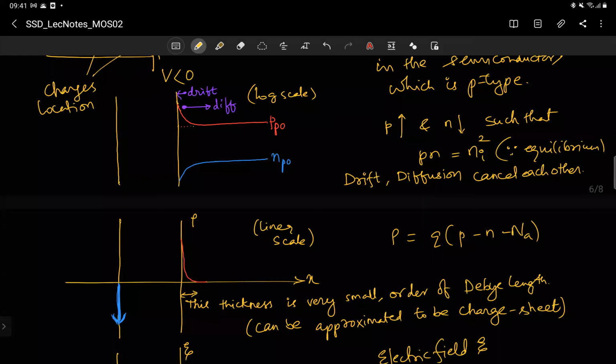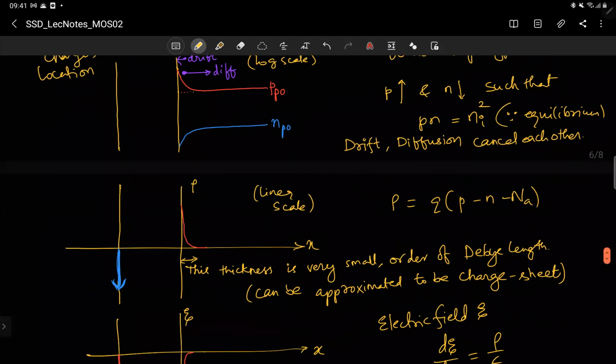But you should actually put the concentration of the majority carrier, which is much larger. So this will be a very thin region. Even the semiconductor region you can show like an impulse function, like we show in the metal region, but for understanding's sake, we still show it like this.